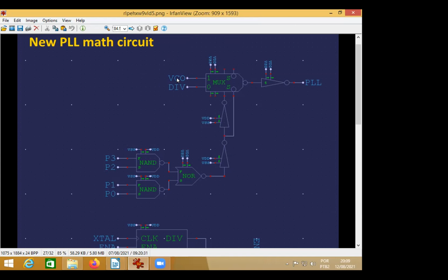So if one of them is 1, it doesn't matter if the other is clocking to 0 at higher frequency. If this one is high during the whole change cycle, we don't have the problem of this one switching faster, because that one will control the output. So it's not important that we lose some cycles.